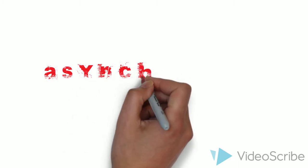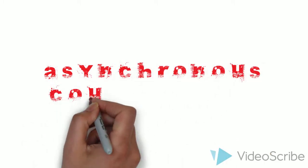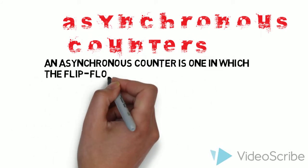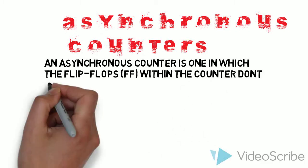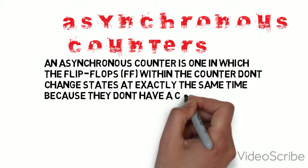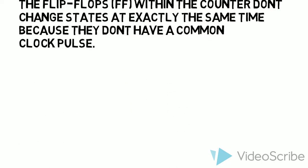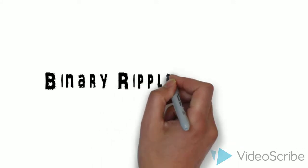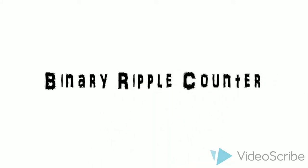The asynchronous counters. The term asynchronous refers to events that do not have a fixed time relationship with each other and generally don't occur at the same time. An asynchronous counter is one in which all flip-flops within the counter don't change states at exactly the same time because they don't have a common clock pulse. Another term for these counters is ripple counters.